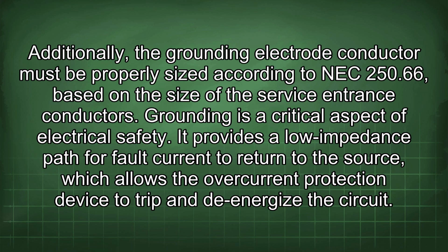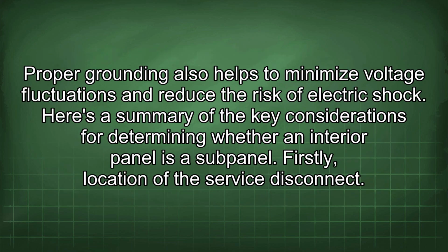Grounding is a critical aspect of electrical safety. It provides a low impedance path for fault current to return to the source, which allows the overcurrent protection device to trip and de-energize the circuit. Proper grounding also helps to minimize voltage fluctuations and reduce the risk of electric shock.